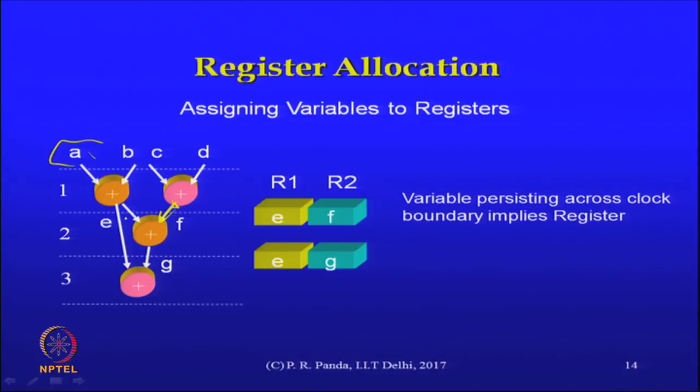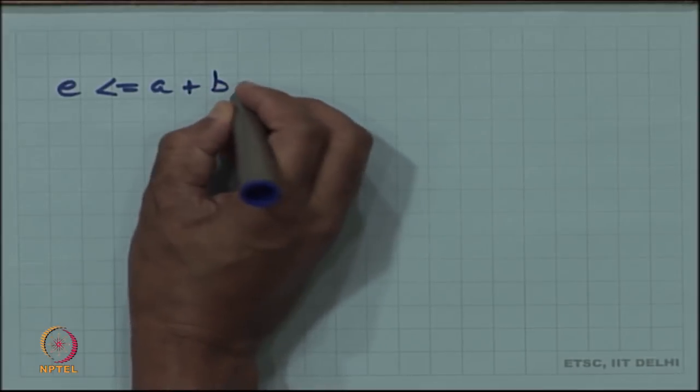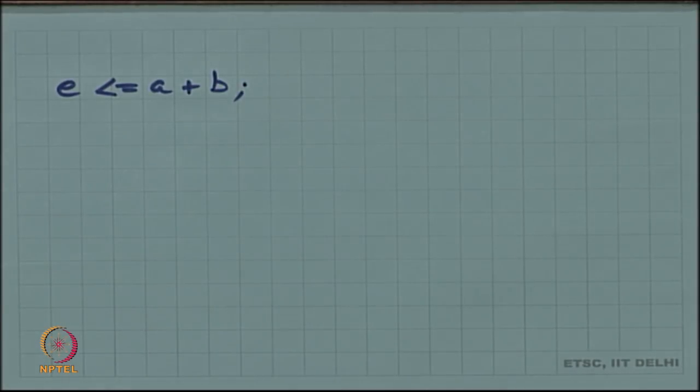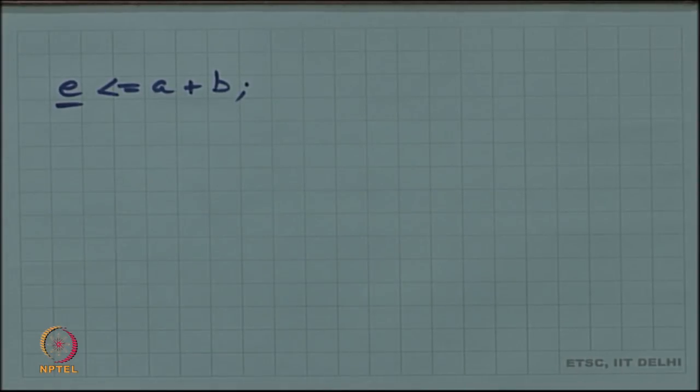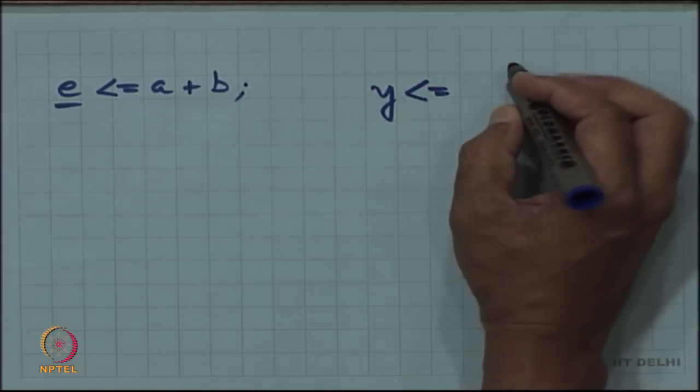Remember, these variables are inferred irrespective of whether or not you explicitly had them declared in the code, right. So, you could have variables of this nature. I have them as signals now, but in fact even if they were process variables, the treatment would still be the same as far as the synthesis is concerned. So, it could be that you have this E and F being explicitly declared in the code. It could also be that you have a statement like this.